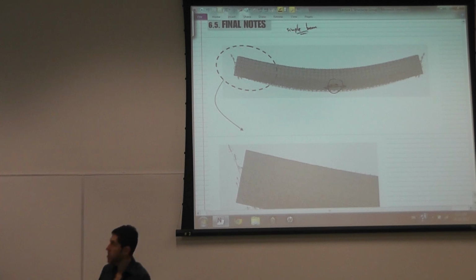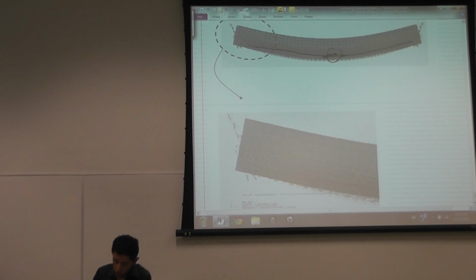And so if you were designing this, if this is a concrete beam, you put your steel bars at the bottom here. Closer to the support, that's when the bending decreases and the effect of the shear increases. And that's when you start seeing that the principal stresses are more aligned with an angle. And so if this concrete beam would crack, it would crack perpendicular to those principal stresses.